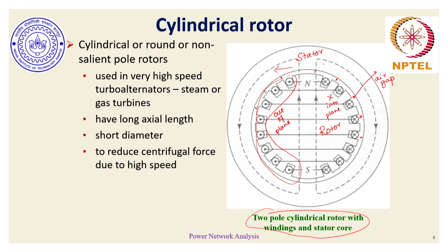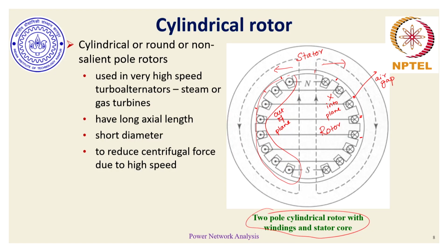Whereas for the windings which are present on the right hand side, the current is into the plane, so the thumb points downwards, while the fingers would curl in the direction of the corresponding magnetic flux. And now if we see the corresponding magnetic flux, let's say for one particular winding, if I were to draw, the corresponding magnetic flux is in anti-clockwise direction, whereas for the counter winding present over here, the corresponding flux, they are all closed field lines, so the corresponding magnetic flux is in clockwise direction.